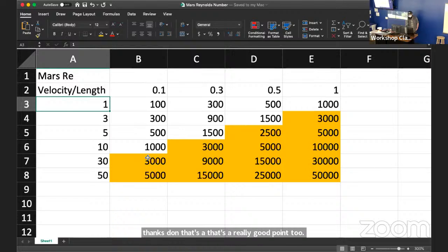Law of the wall also assumes that the atmosphere is neutrally stable, which isn't always true either. So this is telling us, I think, that if you're going to make a measurement of roughness using the law of the wall, which is something we've come back to several times during this conference, you need to choose your locale very carefully so that you have the right roughness already. And you need to make measurements only when the wind speeds are high enough and when the atmosphere is neutrally stable. Otherwise, trying to fit a law of the wall profile to estimate shear is not going to work.